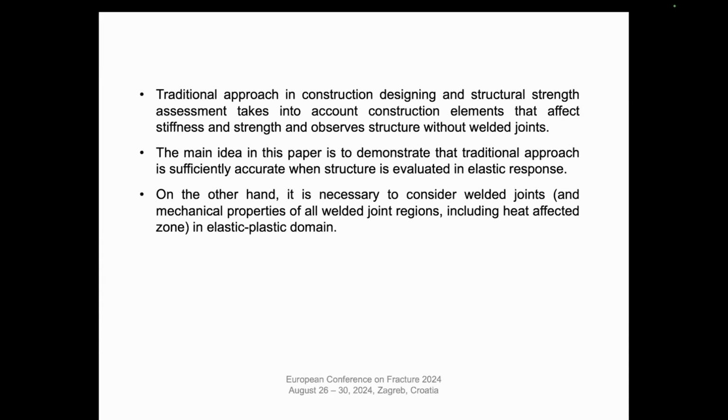But welded joints affect structural rigidity, especially in the plastic domain. So the main idea of this paper is to prove that in the elastic domain it is allowed to ignore welded joints, whereas in the elastic-plastic response, welded joints should also be included in the calculation.